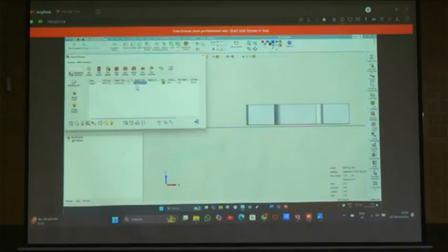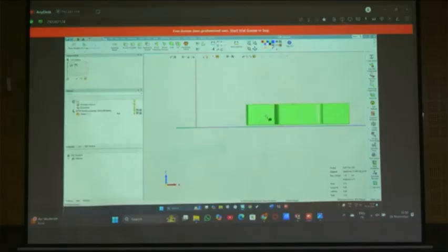If I am going with the wire cut EDM, I can apply the solid support so that I can remove it. But to reduce the post processing time of wire cut EDM, and to reduce the material, I can apply some other supports also, like wall type supports and all those things. First I will apply the solid, later we can see the other supports. So I can go with the skirt support, that is also solid only. Like in between bases we can apply the skirt support. So I will select this.